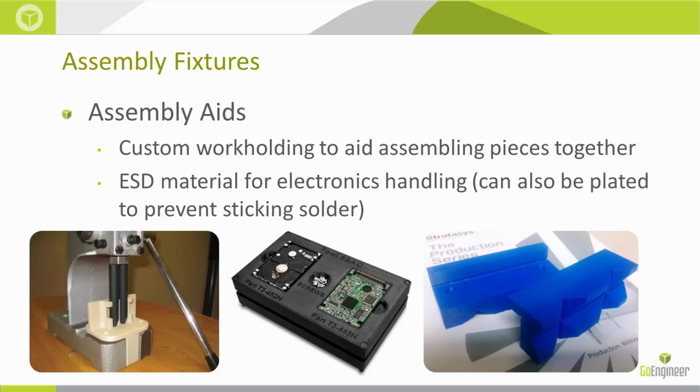So I designed this up in SolidWorks pretty quick and printed out a set of soft jaws for myself and a wrench. I put a couple cavities on the back of the jaw so that it would stick to the vise. I thought that was clever, but again, that's something that is actually used a lot more often than you would think: the idea of using magnets with these parts. But it helped me do the job, and I didn't have to spend any extra money on the custom size wrenches and whatnot. That particular part is made out of ABS.